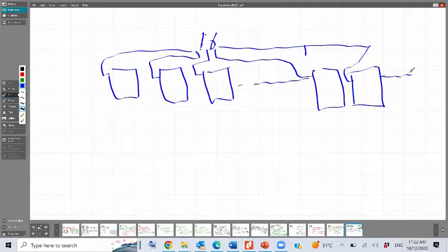If I have one output that is D15, it will be parallel in, serial out. If I have 16 outputs, that would mean it is parallel in, parallel out. But with shift register, everything is moving to the left or the right. I can have the choice of making shift right or shift left.